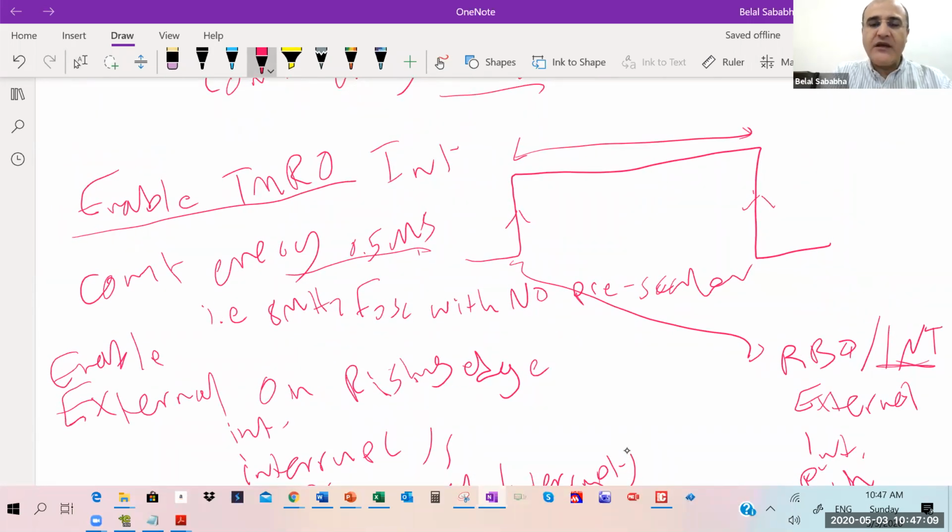And let's say this value was 0x34. Then timer 0 continued 35, 36, 37, then FF, then it overflowed here. Overflow after FF it went back to 0. But then it counted from 0 to FF and overflowed here and overflowed here.